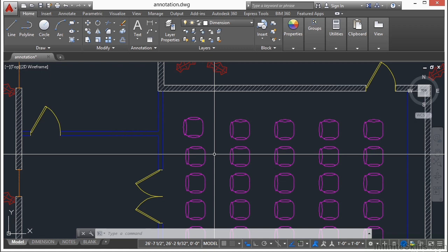And it's also a good practice to create a block library somewhere. That's a folder where you have all of your blocks saved in it. Organize it with subfolders so that you know what they are. Like make a subfolder of furniture, so all of your furniture can go there. Make it whatever it is that you need. You can keep it there and you can organize it so that you can find them and use them in future drawings. If you make a block for a project that you're working on, it might be a good idea to save that block in your library, because if it was important enough to make for this one project, it might come up again and you might be able to use it.